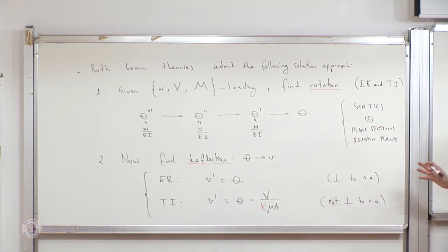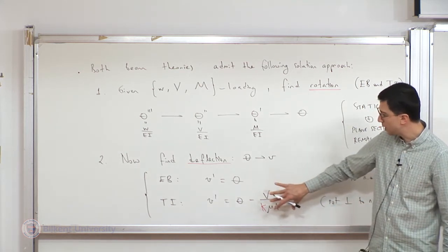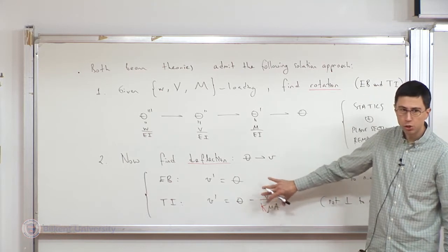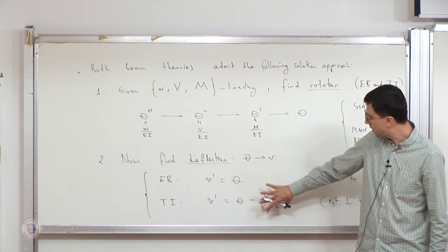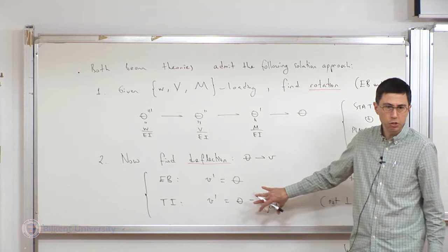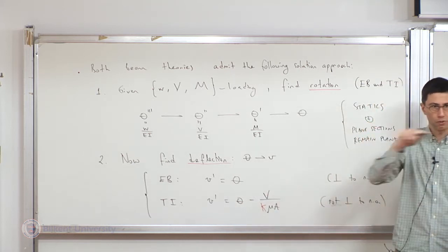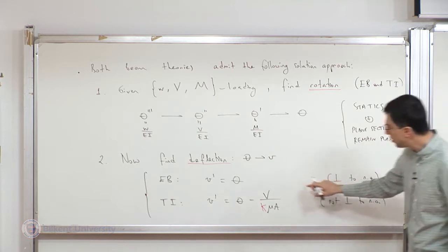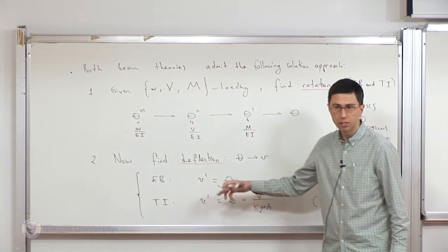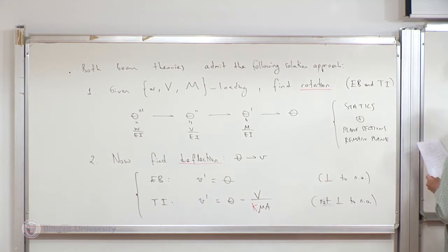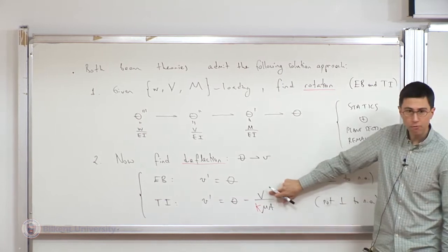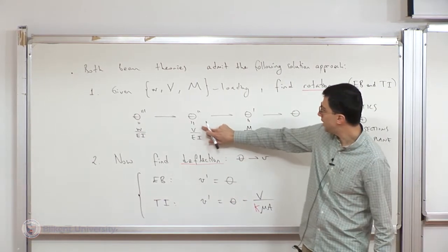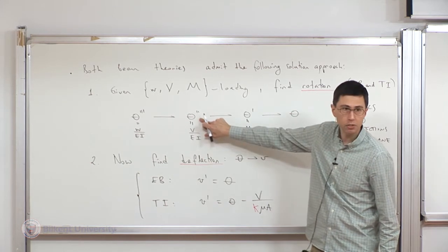So now let me just highlight, I've said several times that there is an additional contribution that always has to do with shear. We see that contribution here. And we said that this contribution is not important if the beam is really slender. In other words, the height is very small with respect to the length of the beam. So by looking at this term, we can do an order of magnitude analysis to make that more clear. And let's do that. So now first, there is this term V appearing here. But when I look here, I see that V is equal to EI times theta double prime. So I'm going to make use of that.